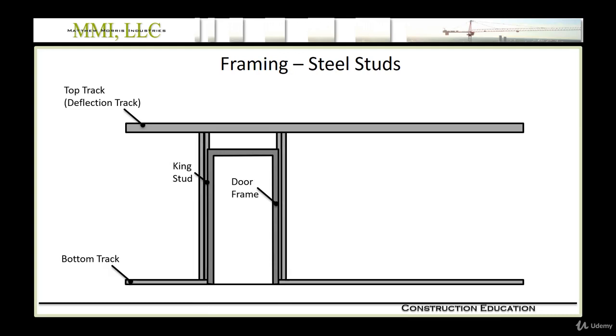And usually those are doubled up or tripled up. And this provides strength, in particular with a door. When someone slams the door, you don't want to have a single stud there. You're going to get some movement in your wall, cracking of drywall, and you don't want that. Also at your openings, you have a header horizontally across the top of the opening.